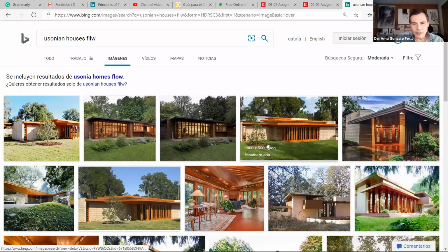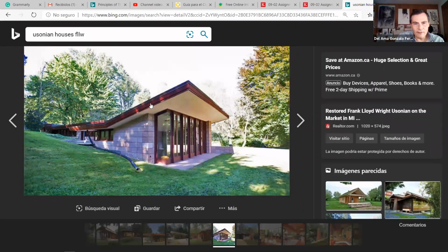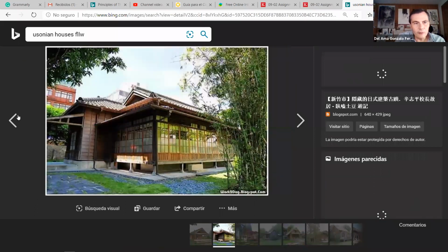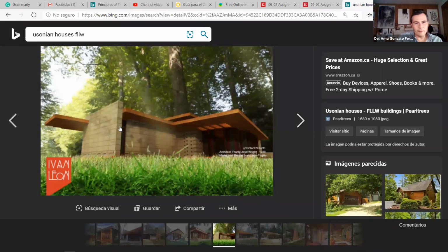Okay, and if you can see all these single-family houses, they have the same concept. They have large windows facing south, and they have these overhangs here. But if you look at the north elevation, it's completely different. The north elevation has very small openings like this, and it doesn't have overhangs because we don't need overhangs in the north elevation. Okay, but this is the contrast.